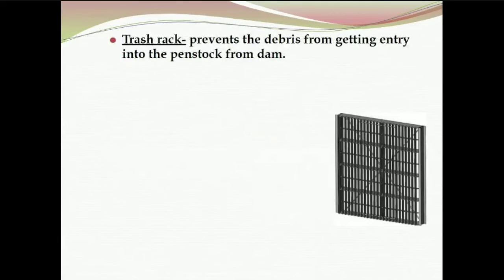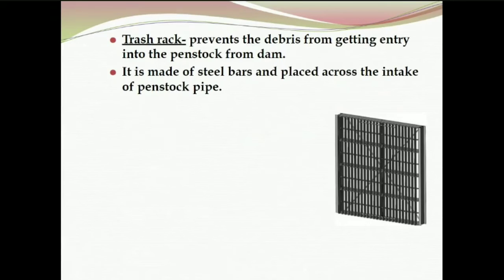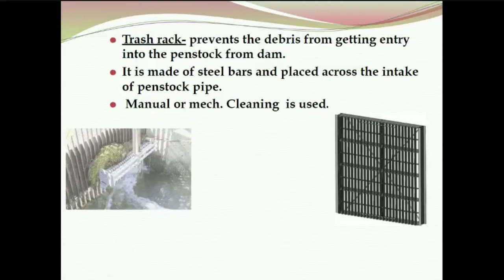And trash rack. It prevents the debris from getting entry into the penstock pipe from the dam. It is made of steel bars and placed across the intake of the penstock pipe. Then it has to be cleaned regularly. Manual or mechanical cleaning is used.